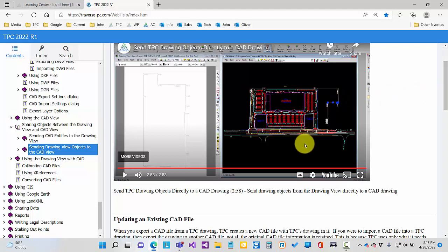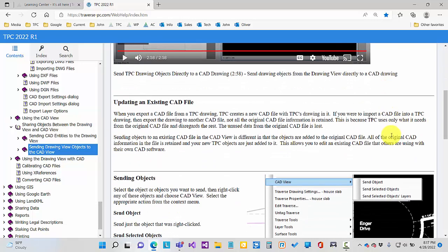Remember, we supplied the original survey information for this project, and they designed it on our coordinate grid. So when we got the designs back, they were ready for stakeout, which was great. But we've talked in this webinar about doing this calibrated and uncalibrated both, and we understand it's really not a difficult thing to account for the differences in the coordinate reference systems now.